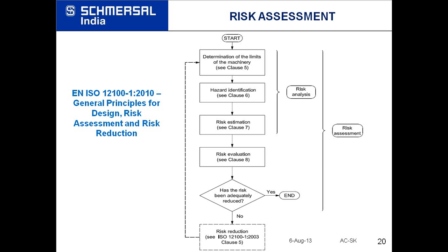So the user doesn't know that this machine can run at 2,500 RPM. There may be an instance after 10 or 15 years of that machine, that because of some problems in the wiring or certain requirements, the machine may run at 2,500 RPM, and the operator may not be prepared for that high speed, which may lead to accidents.